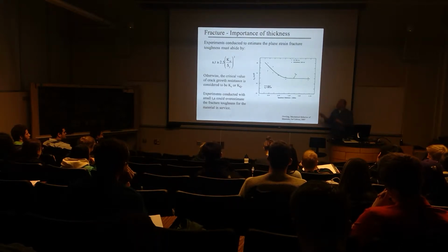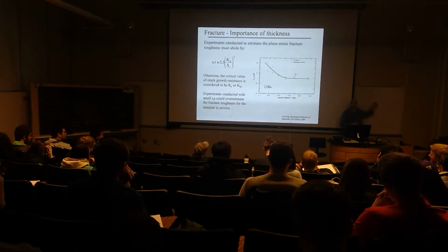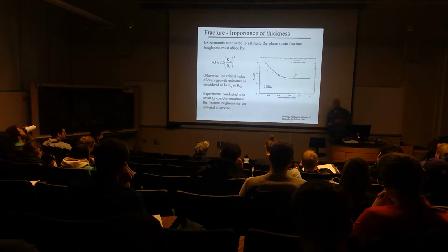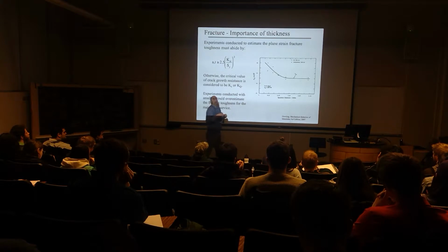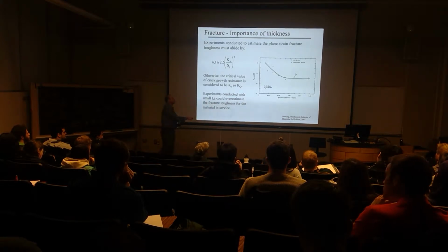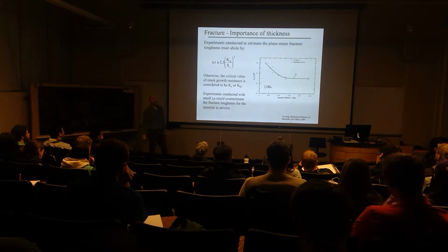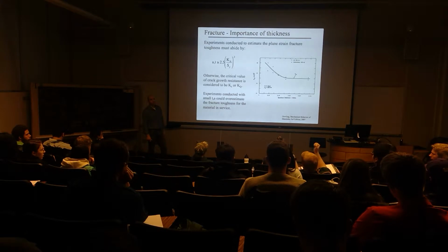Whereas in this case, what we're doing is we're trying to start a crack by placing a notch and then sawing the notch with diamond paste and getting it to be very sharp. But then still what will happen is that the crack will start to ovalize, and for very thin bodies, it'll start to develop plastic deformation. So the crack development is not necessarily one of those dynamic. So no pop-in is going to be more like it tears apart versus it just pops apart? Or is it?